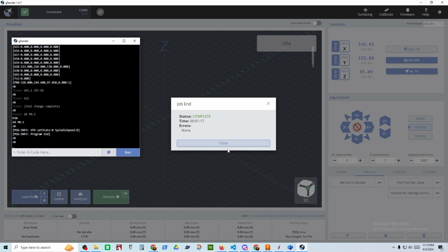So the IR sensor, which is normally open, pulls to ground when it's triggered, just like the tool setter and the 3D probe and your conductive touch plate, all wired to the same pin, which is very convenient. And I'm going to go ahead and show you the probing routine too, because I think it's pretty cool.